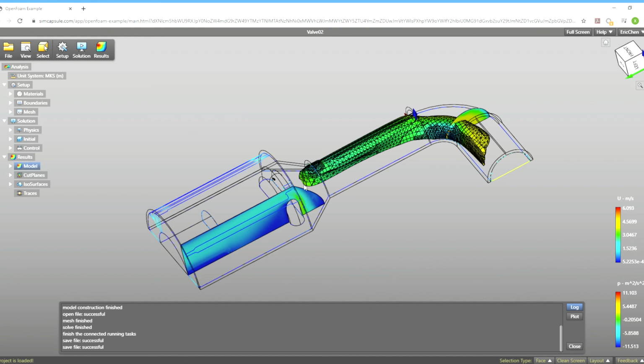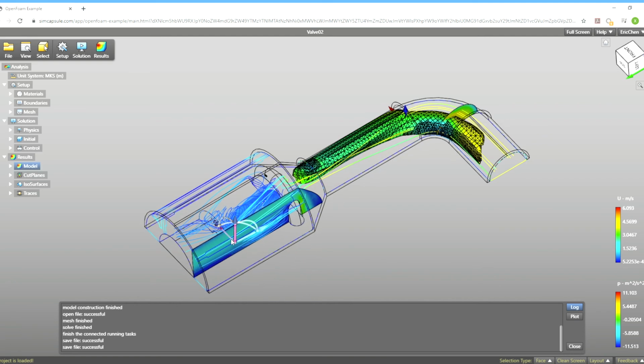Now we come to the most interesting part, create traces. You can add them by free pick, click any shaded or mesh surface. New trace line is generated immediately. Right-click to quit this mode. Or you can build traces from specified pattern. For instance, line pattern. After traces are generated, seeds also can be modified with locator. Remember, traces only can be picked from other cut plane or ISO surfaces.